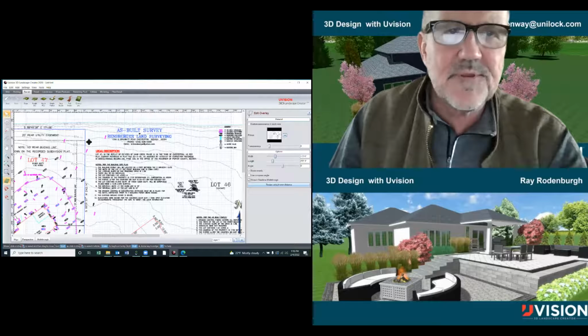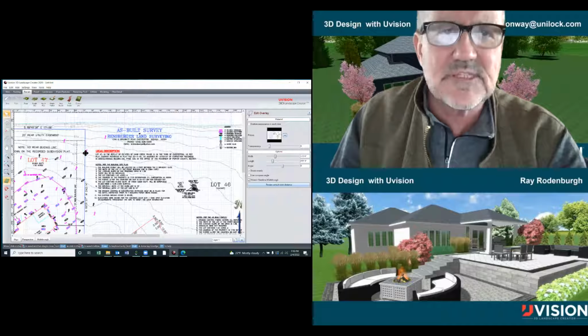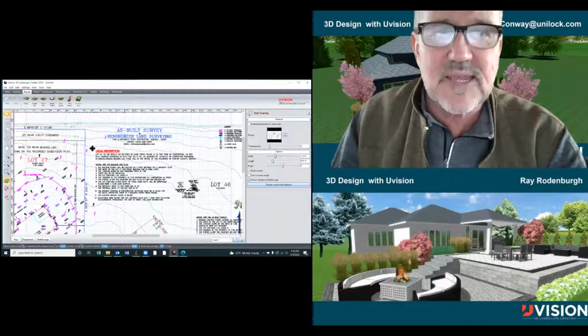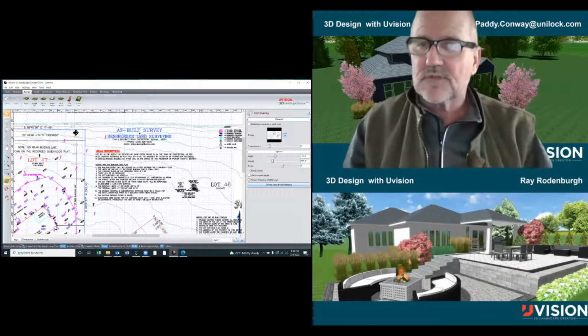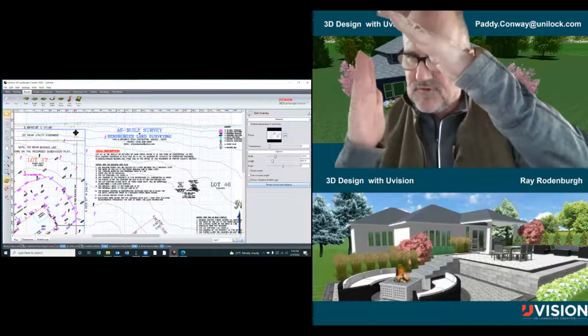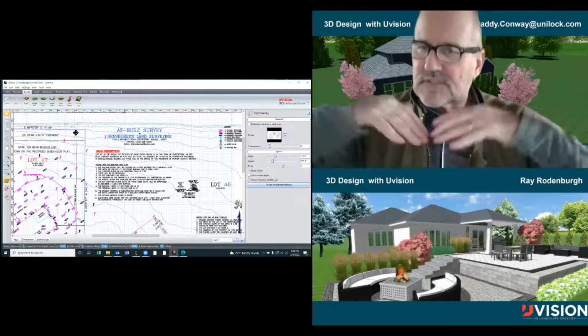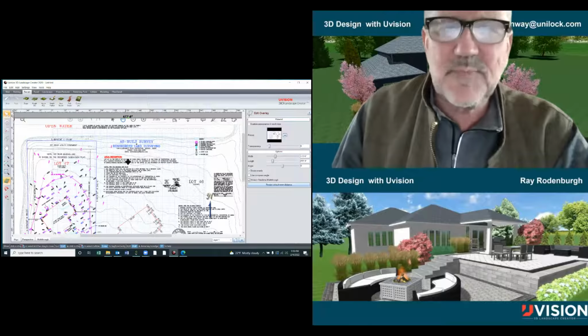Yet when I get up to here, 673 would be at the top of my mouse axis here, 674. You can see the difference between 674 and 675. It's wider, over, let's say, 5 squares, which is 10 feet. Yet 670 to 671 is less than 2 feet. So it's going up a foot every 2 feet. As I get onto the land, it's going up a foot every 10 feet. So it's calmer. Now, what does this mean to my design?